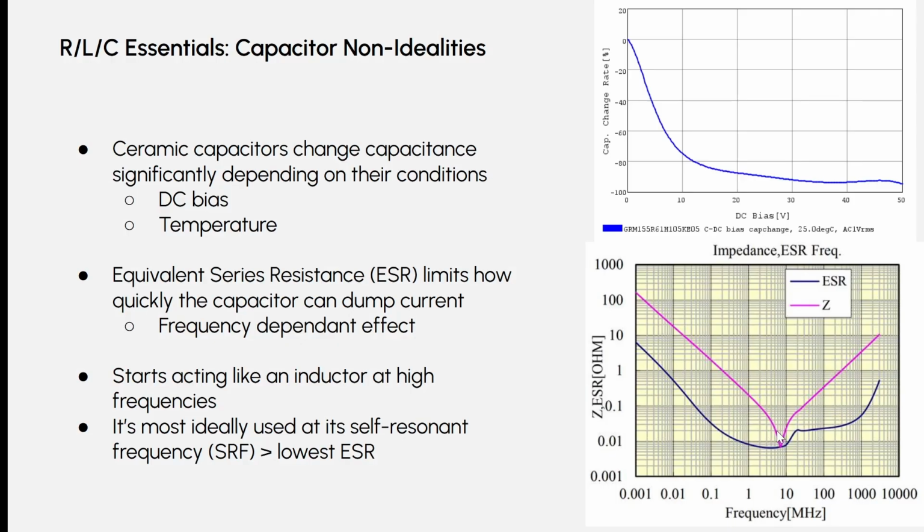What that means is this particular capacitor we're looking at ideally would be used to filter some frequency around 10 megahertz. That would be phenomenal. It's going to have amazing resistance. But if you're trying to filter like 10 gigahertz, which is obviously an extreme case, it actually behaves like an inductor. It completely switches and behaves like an inductor at higher frequencies. And really what you're seeing is mostly capacitance, and then the inductor starts happening and they're competing with each other. And then you get a really good, small resistor, and then you start getting more of an inductor.